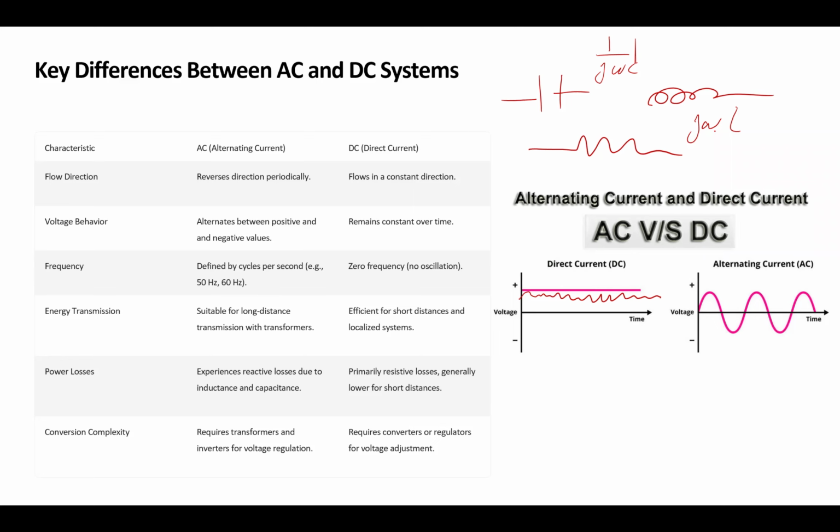Now, for energy transmission, the dominant impedance in a DC system is resistance, and in the AC system it is normally inductance. When we talk about resistance, we talk about the wire. In short distances, the resistance is low, so the impedance of a transmission is low, so DC works perfectly. It's better than AC. But in long distances, not so much.